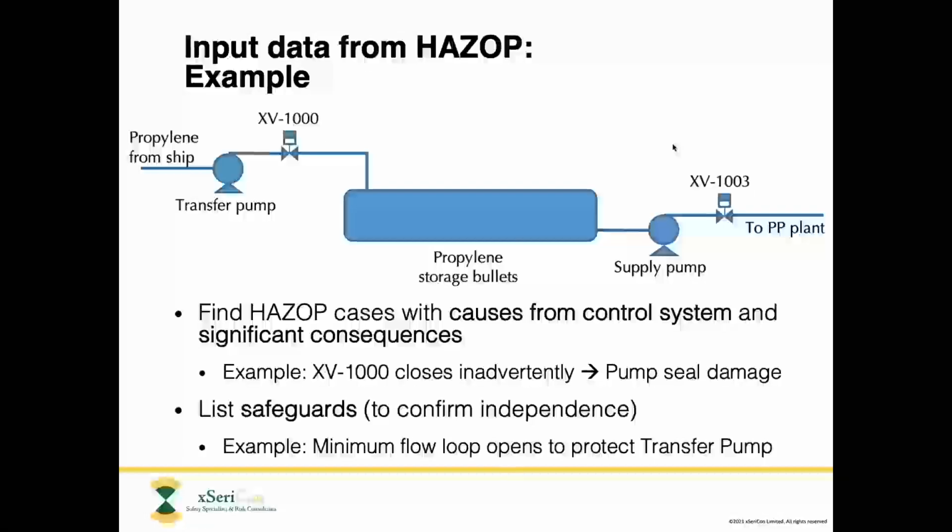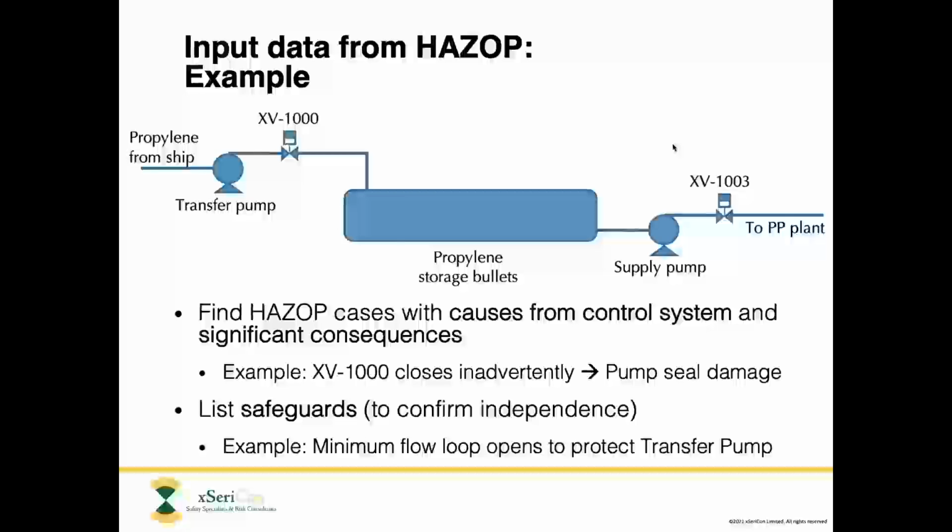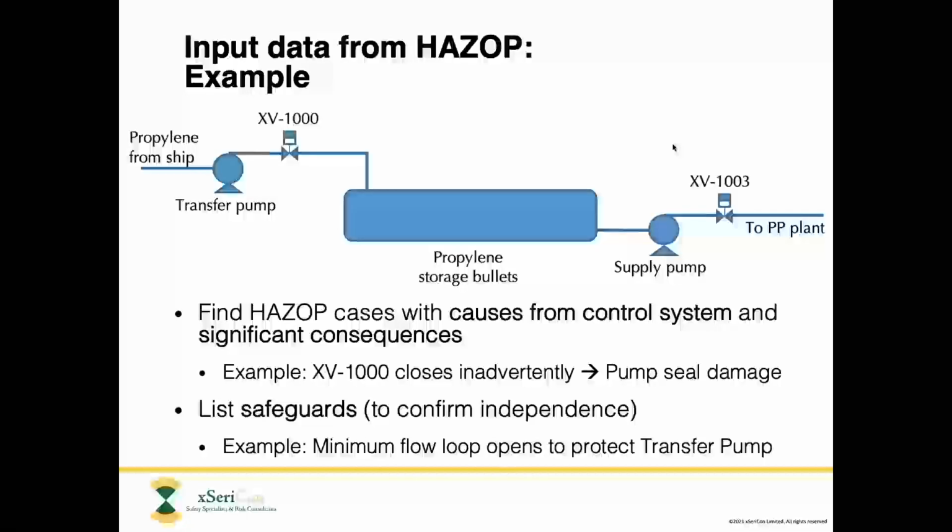So we need plenty of detailed information about what is actually there in the system, which cards, which consoles, which modules, etc. Because we will be asking quite a lot of very detailed questions about it, which even the C&I team, control and instrumentation team, may not be familiar with the system to that level of detail, especially if it's a legacy system that's been around for a few years, which is quite commonly the case in a CHAZOP study. And then the other thing we need is the architecture of the control system, including the network connections.